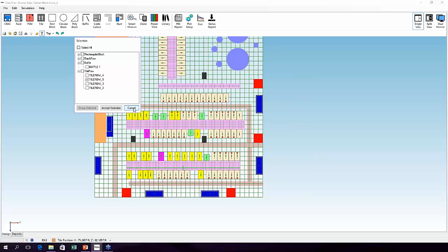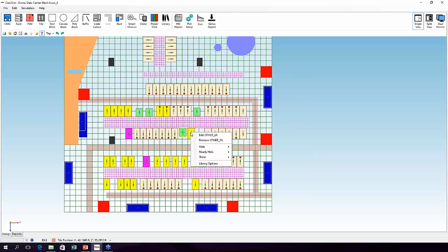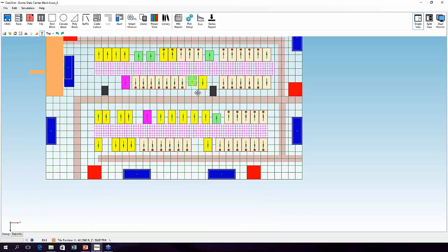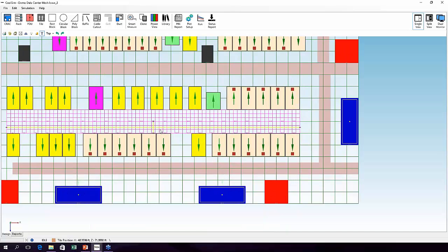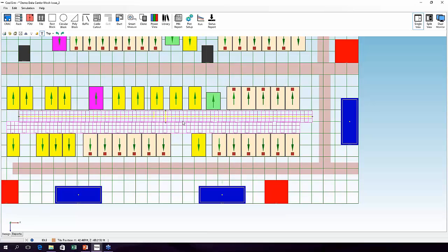Now, the most common thing that happens is that people double paste things by accident. These are often accidents. So let's see what we've got here. Now, the way to tell if something's on top of another, you can't have one object on top of another object because the inlets and outlets will get blocked, and it will fail and solve, or fail and mesh as well. It can't get a mesh on it. What I always do is just pull it, see if there's anything behind it.